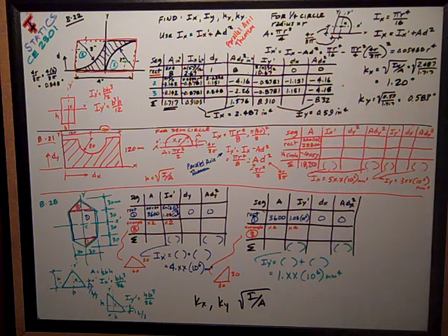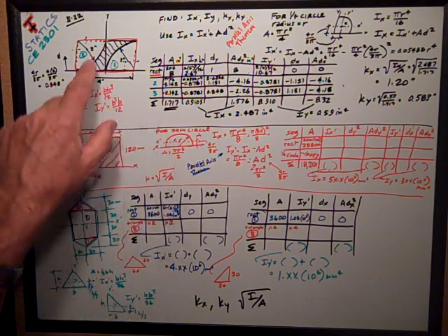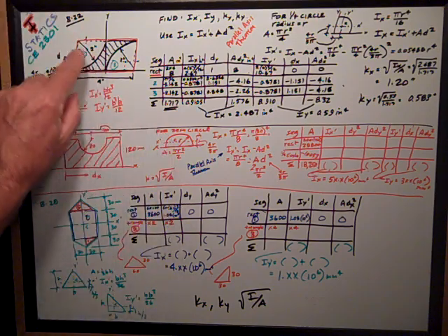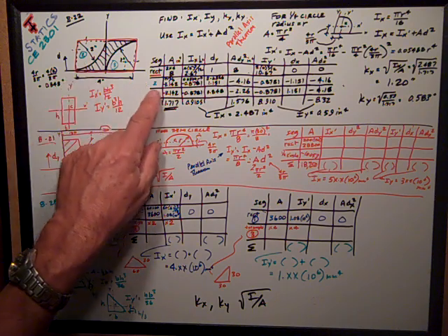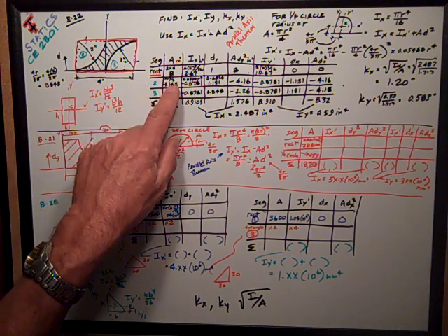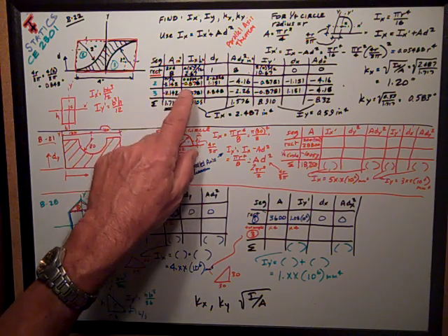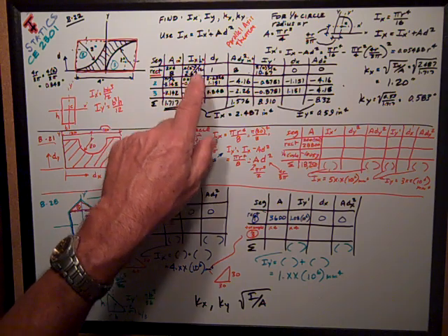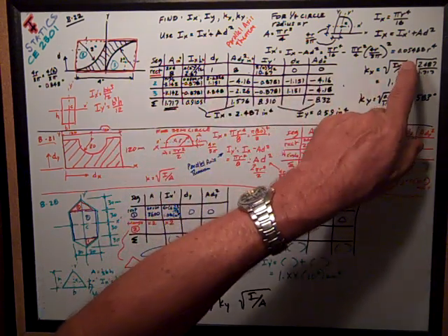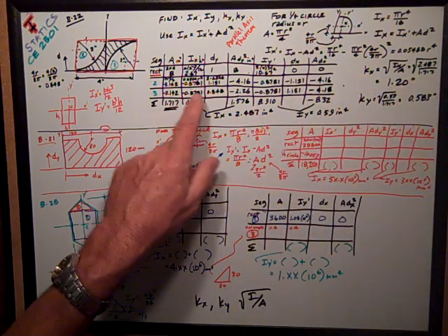Now a little bit more complicated, I got to look at those little quarter circles, and it's not symmetric, so I have to kind of break them up into two parts. Area 2 is pi r squared over 4, negative, essentially. Its own centroidal axis moment of inertia is this 0.05488 r to the fourth, which is negative.